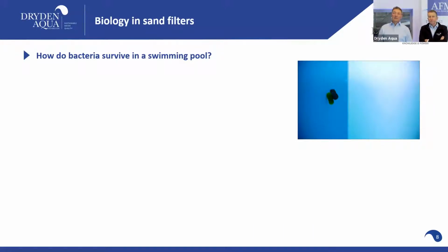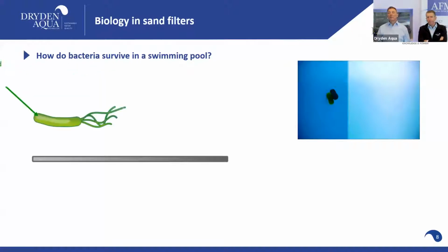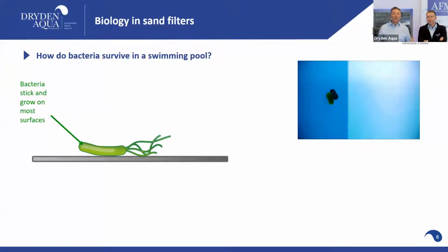So let's start with this. In each pool you have heterotroph bacteria. Heterotroph bacteria, again, are bacteria that feed on organics and produce something inorganic. These are bacteria that can grow very quickly. If they have enough food and nice temperatures, 30 degrees, they double every 30 minutes. And the first ones, the pioneers, are the Pseudomonas. They are swimming in the water.